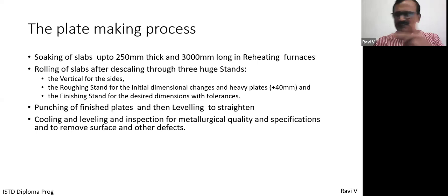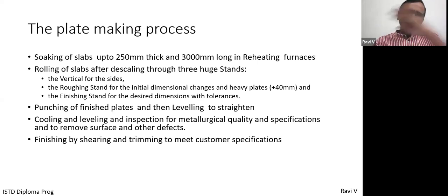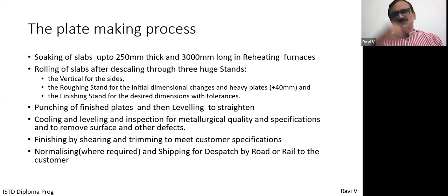And then it is checked for any surface particles, removing the dust and all that. Then once it's all done, it is finished by shearing and then trimming to the specifications required by the customers. Some of the plates, depending upon the requirement of strength, are normalized and then shipped for dispatch by road or rail. So this is typically a small brief about the process.